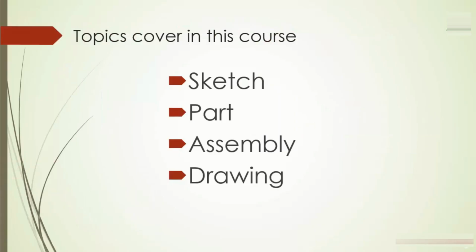As this is an essential training, I will discuss these core important topics: sketch, part, assembly and drawing. If you want to make any part, you have to start with a sketch, then convert that into a part, then from that you can make an assembly, then from part and assembly you can create a drawing. So how to create a basic or intermediate type of sketch, or how to transfer that into the part level. Then inside the part level there are many nice different tools available, and how to work with them.